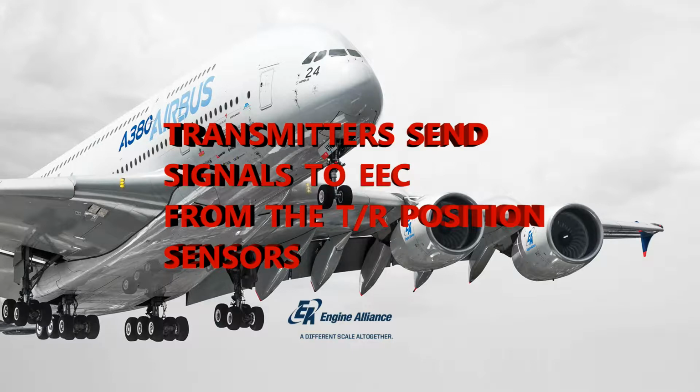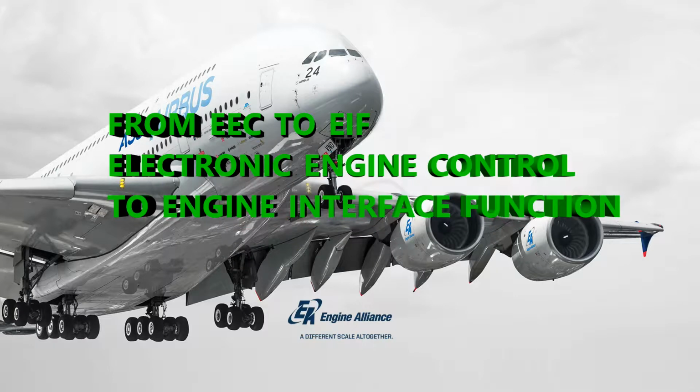So you've got those 2. From the EEC, it then goes to the EIF applications so that it can give the commands correctly for everything else pertaining to the deployment of those thrust reverser cowls. Now, for example, if the aircraft's on the ground, depending on what position the thrust reverser is in, you're going to have an EIF application that's going to send those commands to the E-track.